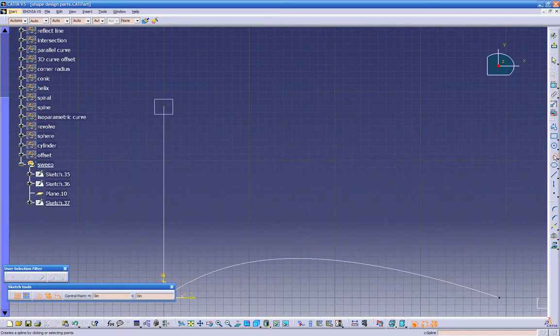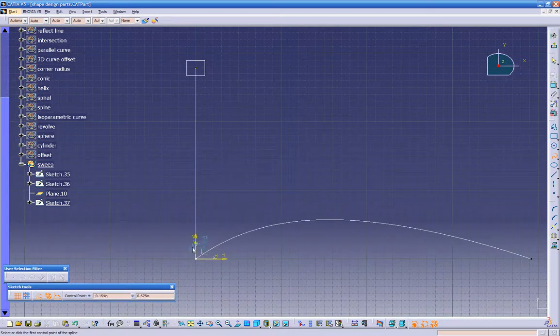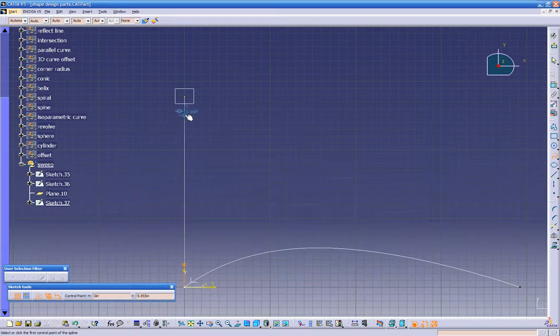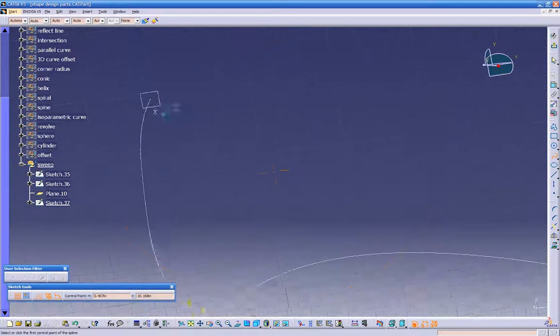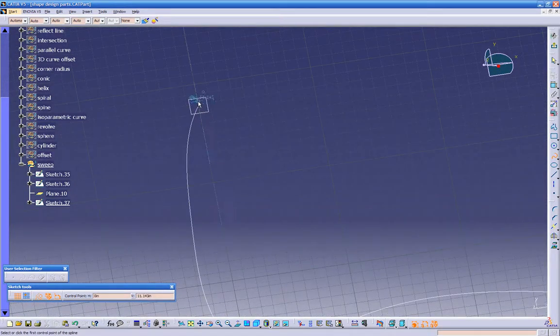and watch the difference. Right now, if I want to go here, it's gonna snap onto my point. See, I got like a full moon. The reason we see this blue right now, because this is our XY coordinate axis, but I needed to create my spline right at the end of this. So that's why I have to project that point into my sketch. So right now I know I'm right at the end point of that. And I have to make sure that I turn this back on right now.